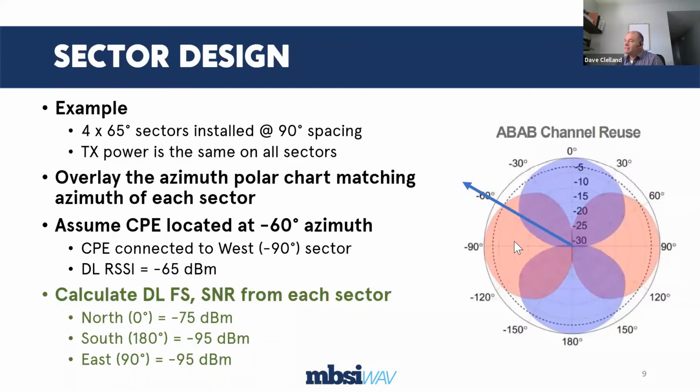So this is why in some systems, such as an LTE system, when the CPE makes a decision to join a sector, if there was an anomaly going on right at this moment with the west sector, and the north sector was actually a better quality signal than the west sector, maybe because it's a little less signal strength or something, the CPE might want to join the north. It might be perfectly happy joining the north sector, and even though it's pointed at the west sector, it might want to choose that north sector and would be quite happy connected to that sector.